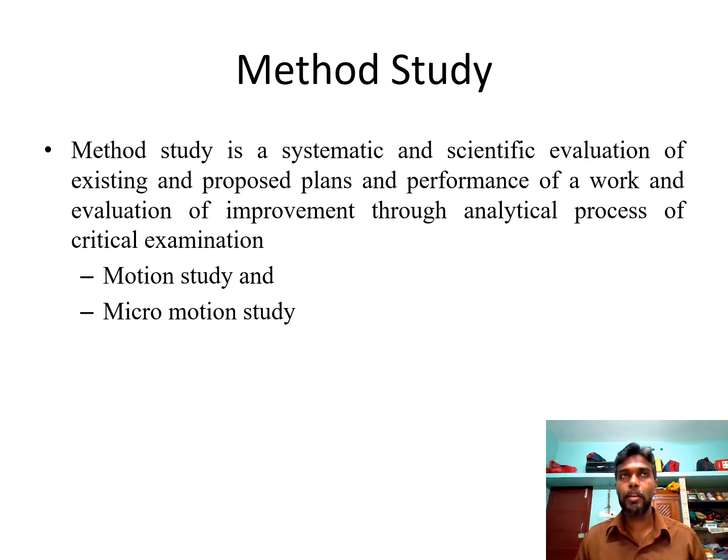Next is method study. Method study was developed by Gilbreth. Method study is a systematic and scientific evaluation of existing and proposed plans and performance of a work, and evaluation of improvement through an analytical process of critical examination. Based upon continuous improvement in the study, this method study was again classified into motion study and micro motion study.